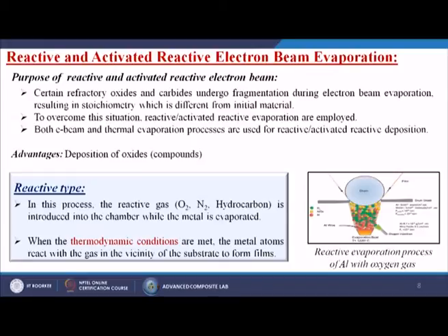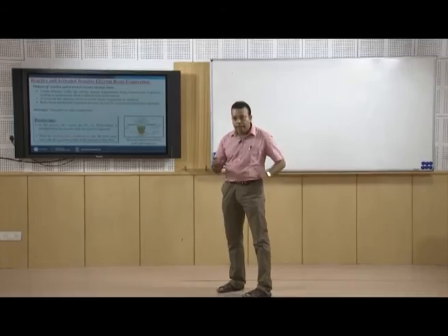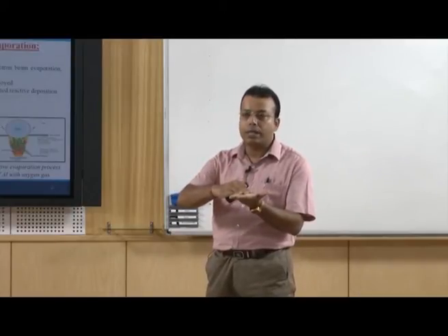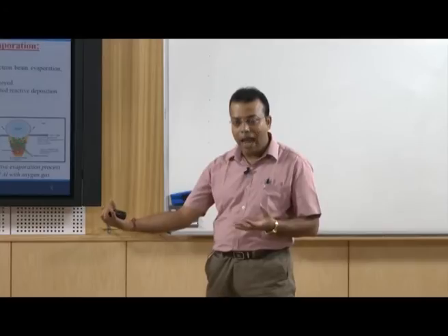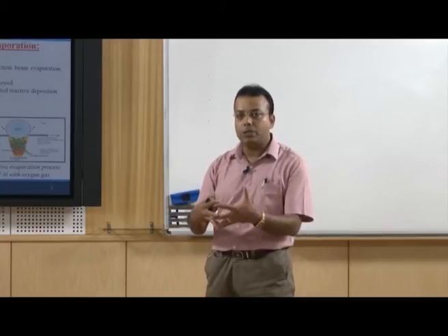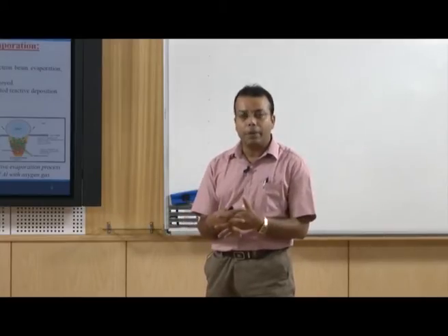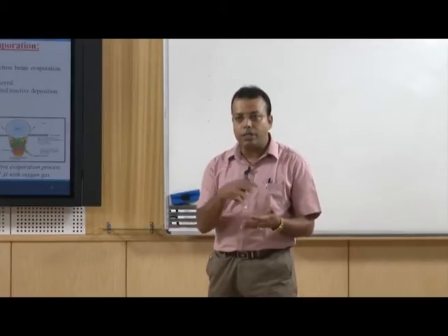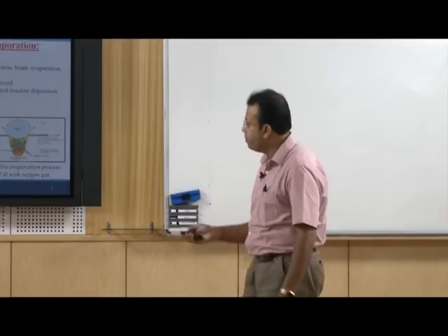So here in this technique, we are using a certain kind of aluminum wire, and then we are using oxygen gas. So it is making aluminum oxide, that is Al2O3, and then that Al2O3 is coating onto the substrate material. So aluminum and the oxygen gas both are mixing together, doing a chemical reaction which forms the Al2O3, and then that Al2O3 is depositing onto the substrate.